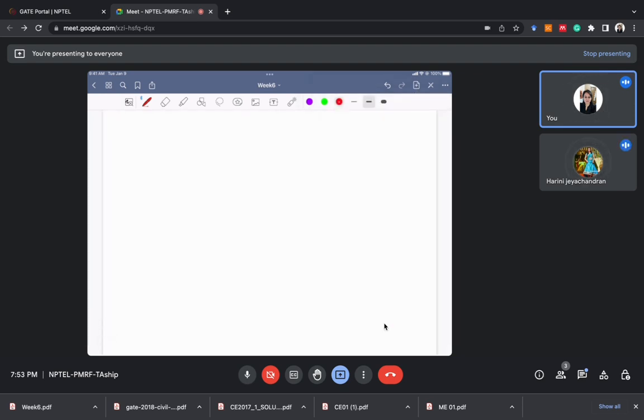So yeah, FD1 we have already calculated, sorry, FDR in this case. So FDR we calculated as 10. FBR you told me is 18.18 kilonewton. Since both of them are in the same direction, we do not need to apply the resultant formula. You can directly add them. So one way of calculating is, since both are in the same direction, you can simply add 18.18 and 10. So your resultant answer will be 28.18 kilonewton.